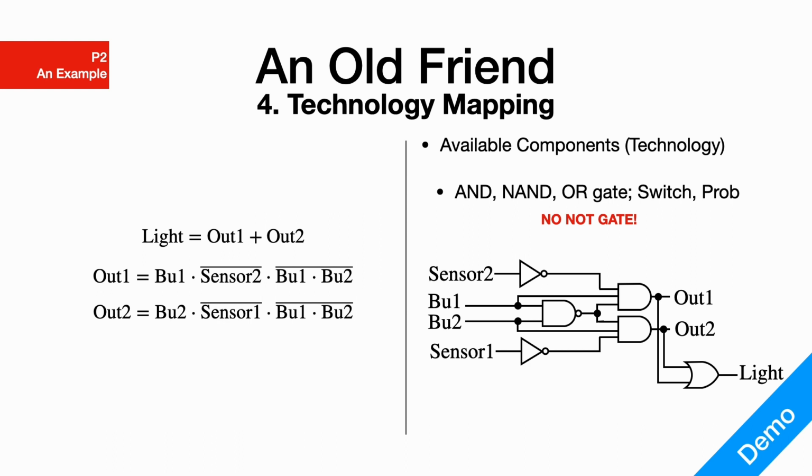Now, one of the simple replacements of a NOT gate is to leverage the existence of a NAND gate. You can replace a NOT gate with a NAND gate and then attach the other input to a positive signal, because we know a variable x AND 1 is equal to x, and then the NAND gate will also have a NOT at the very end of it, the tiny little dot over there. So even though you don't have the NOT gate, you still have NAND gates at your disposal, which you can use essentially to replace the NOT gate.